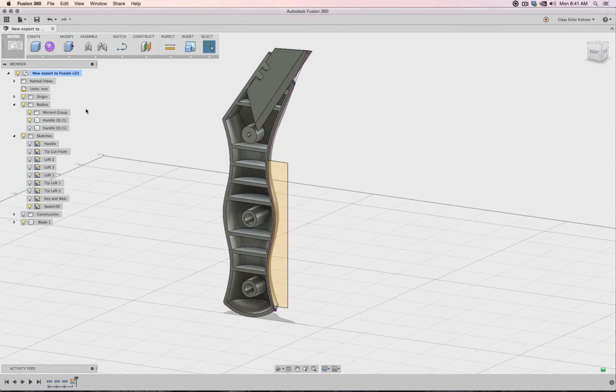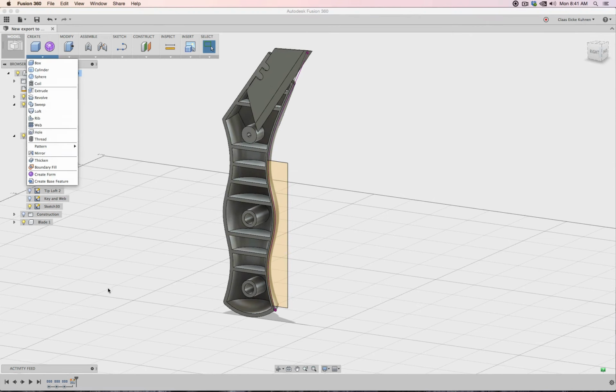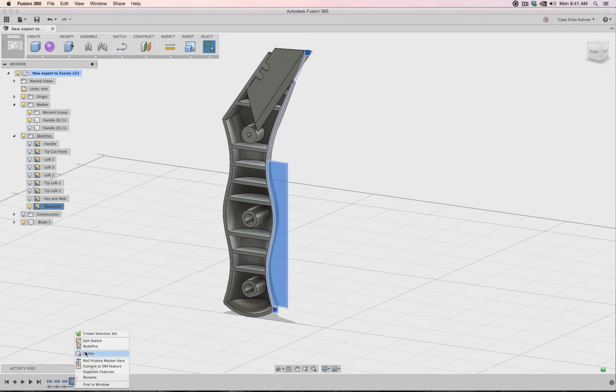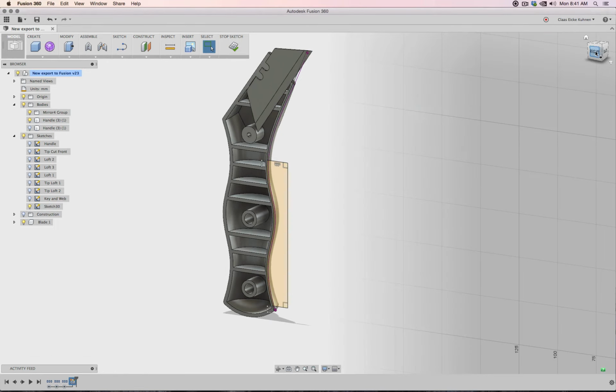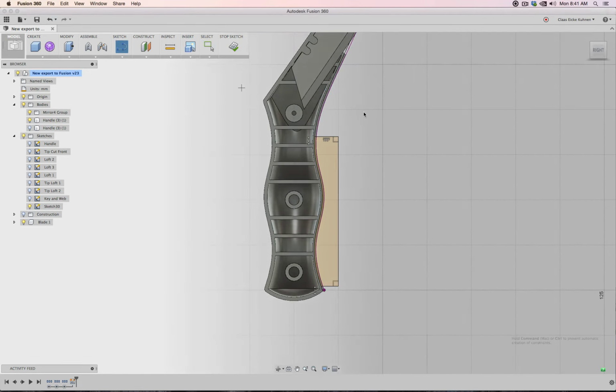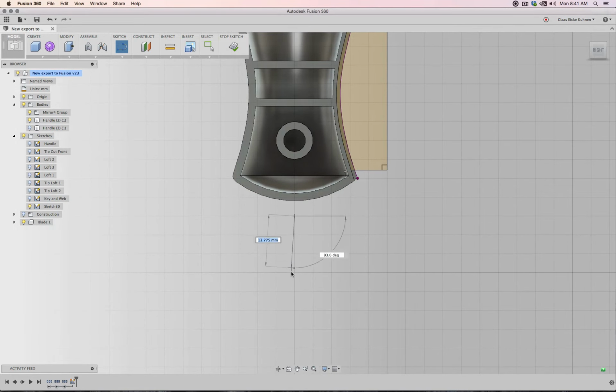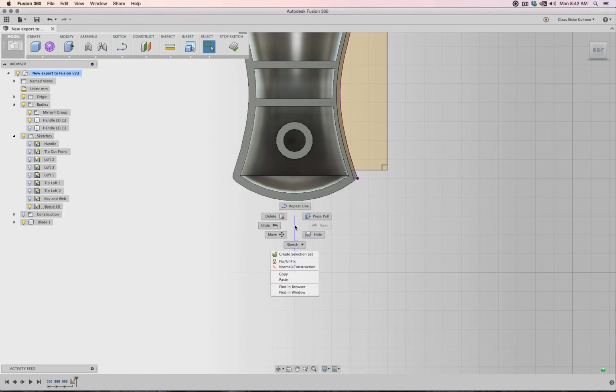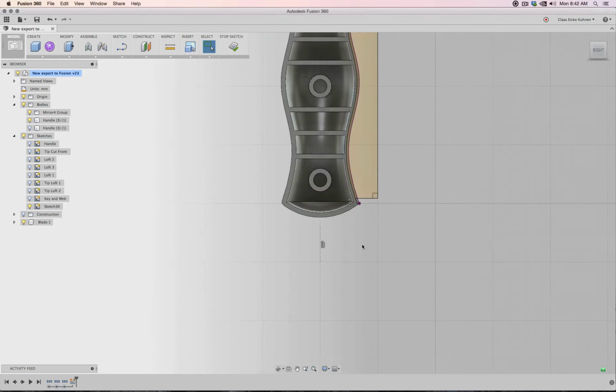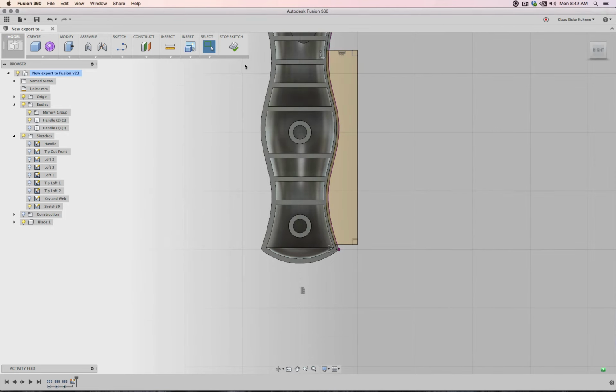So what I'm going to do is I'm going to go back to the sketch. I forgot one thing. Edit, because this is going to be a revolve object, and the revolve object needs an axis, and everything, as you see, is nicely built based on the grid. Another reason why to use the grid. Later it makes everything a lot easier. I make this a construction line because this is actually going to be my axis for my revolve, and it's, because of the grid, perfectly centered at the sketch.